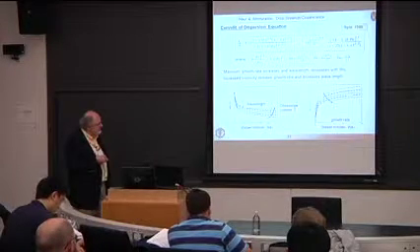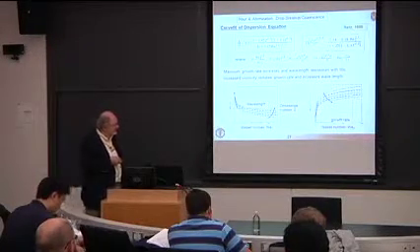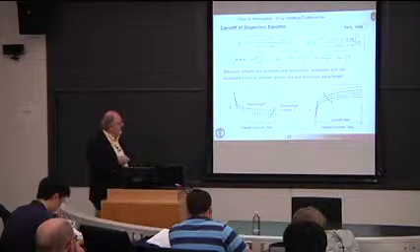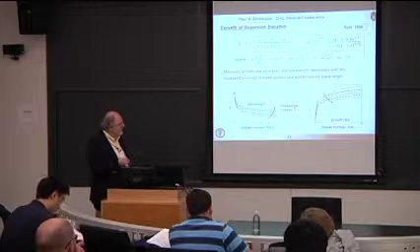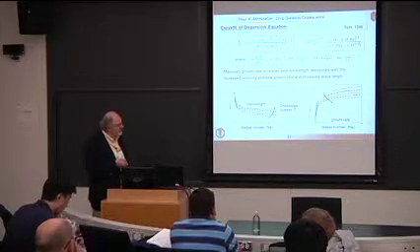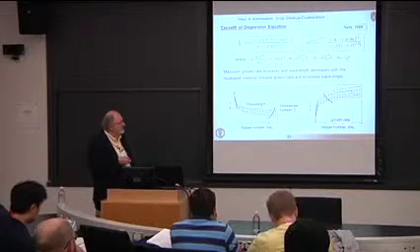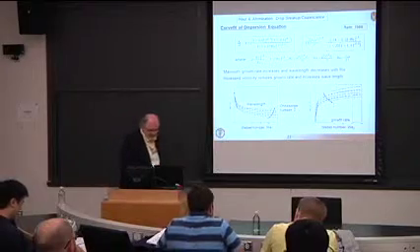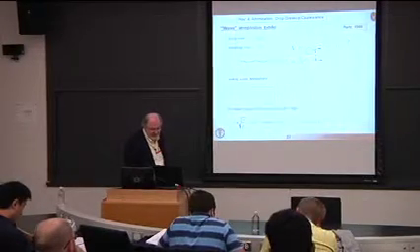If we increase the Ohnesorge number or increase the viscosity, the wavelength also increases. If we look at the wave growth rate here, you see similar, as you might expect, as I increase the Weber number, the growth rate increases. And as I increase the Ohnesorge number, the wave growth rate decreases due to viscous damping effects.